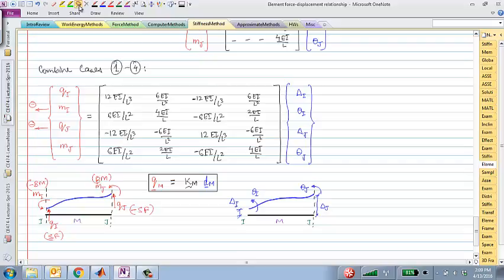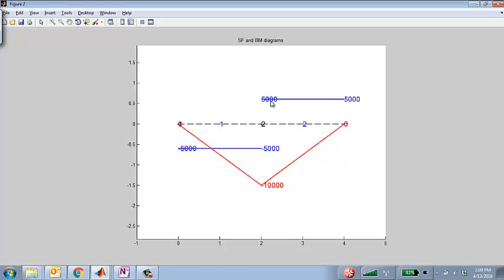Questions, Miles? So I just want to make sure, is that output given like the convention, or do you have to multiply them by negative one? No, you do have to multiply by negative. Actually, the code itself will compute the correct value, and you can see that it actually plots the correct shear force diagram and 0 to minus 10,000. So I'm just combining those two diagrams all in one. The code will already take care of that negative sign. But you have to realize that when you have to do it by hand, those two entries need to be multiplied by a -1 to get the correct shear force and bending moment.